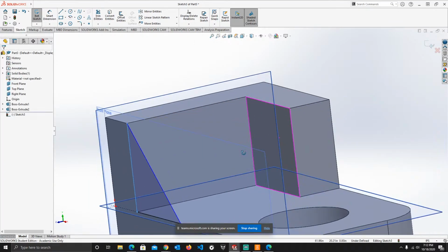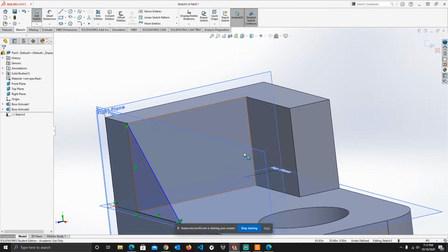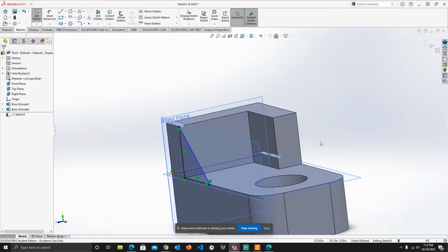Easy. Easy compared to what we had to do if we had not thought about that, right? So it's very important where you're gonna start your figure, because it will make your life easier if you started at the correct position. Otherwise, you have to make reference geometries, or you have to figure another way to make your geometry. And if you messed up for some random reason, then you have to go back and redo your object. So it's very important to understand where things are placed in space and in relation to what as well.